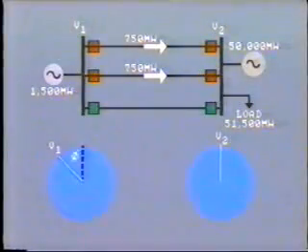As long as these areas are equal, the system will remain stable and ride through the disturbance, in this case the loss of one transmission line. During the dynamic period, the system has quickly settled into a new steady state, with the generator advancing in angle in order to continue to transfer 1,500 megawatts along the two transmission lines.